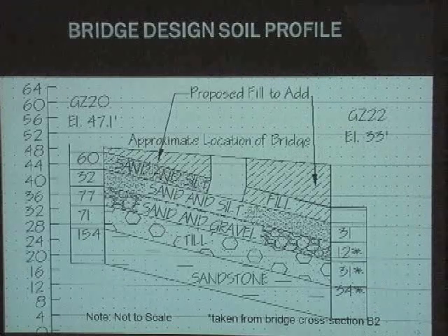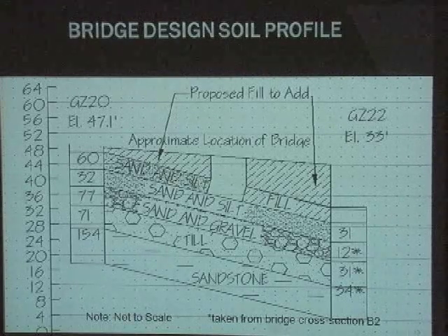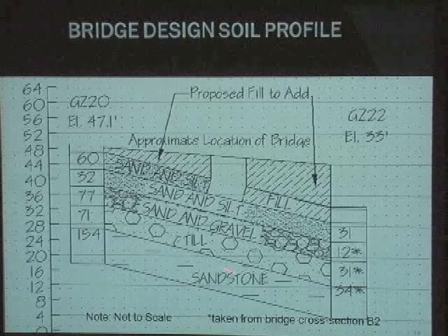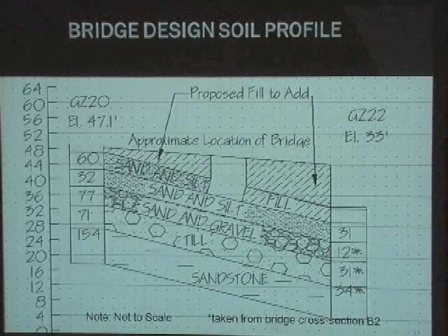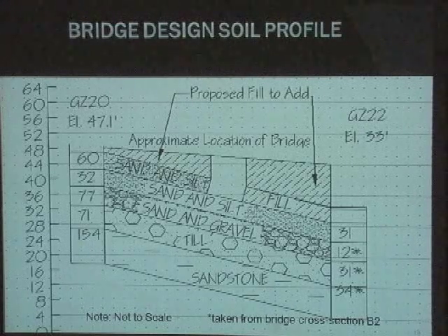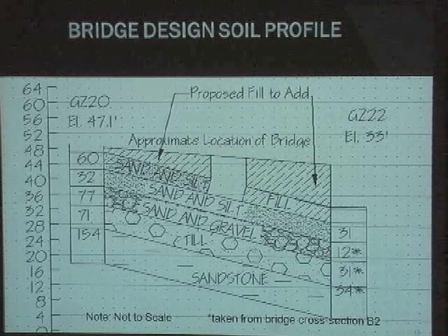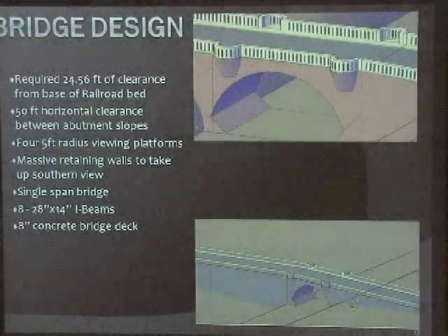One more thing I want to mention that we found that was important was that the sandstone is very weathered. Something we're looking at right now, and we haven't done any calculations yet, is to do some base grouted piles for the bridge, just due to that weathering of the sandstone. With respect to the foundation, we found that for the restaurant and shops it is definitely more economically viable to go with a shallow foundation, and we'll be running some more calculations on that in phase 2 this spring. Moving on to Dave with some more about the bridge.